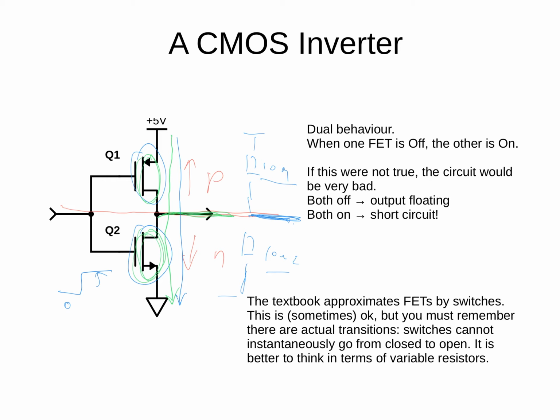But remember that the FETs behave as variable controlled resistors, and so if this FET is initially on so that its channel resistance is very low, as we decrease its gate to source voltage, then we're going to start pinching off the channel, just like squeezing the hose, and so its resistance is going to gradually increase.